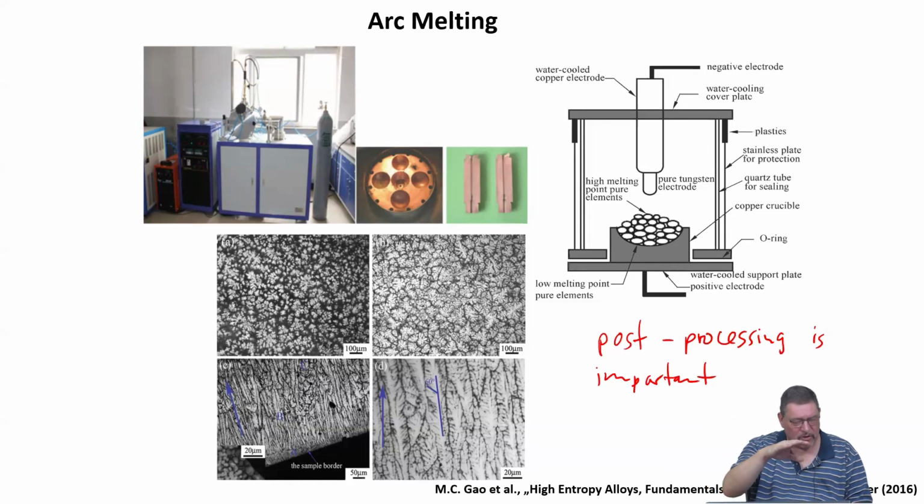Or maybe do homogenization annealing, then deformation, and then again relaxation or recovery annealing, because that will give you not only compositionally uniform material, but also a microstructurally much more uniform material, as compared to not including this mechanical plastic deformation treatment in between. This has a huge impact on diffusion rates, as we found out.